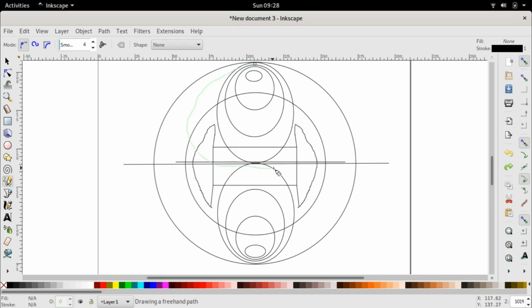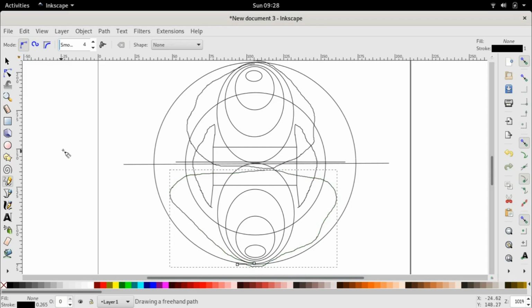This comes in, and from here I can draw another one. And there are many such concentric lines. Now, what is important to understand is in this position of the rotor, when the rotor is horizontal and the axis of the rotor is totally 90 degrees or in quadrature with the axis formed by these stator poles, in that case the reluctance of the flux path is actually the least.